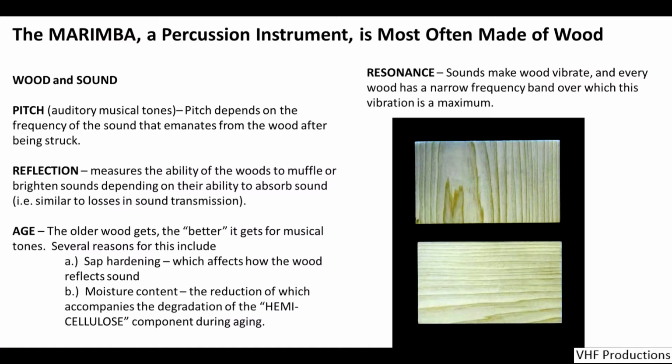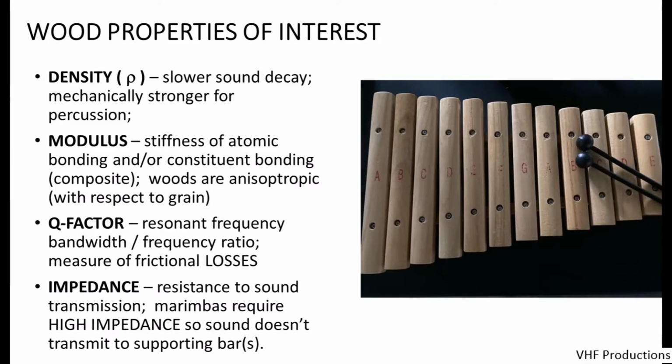If you take a large trunk of a tree and try to cut it with an axe, cutting it perpendicular to the length of the tree is very difficult. It requires an enormous amount of chopping to break through the wood in that direction. However, if we take a section of the tree trunk and stand it so that the cross section of the tree trunk is parallel to the surface of the ground, and now you take an axe and strike it in that direction, you can often split the wood in a single blow. This is due to the change in the orientation of the grains with respect to the direction that you're trying to apply the axe. Highly anisotropic properties. Those differences in properties also translate to differences in modulus values for the materials in these two orientations.